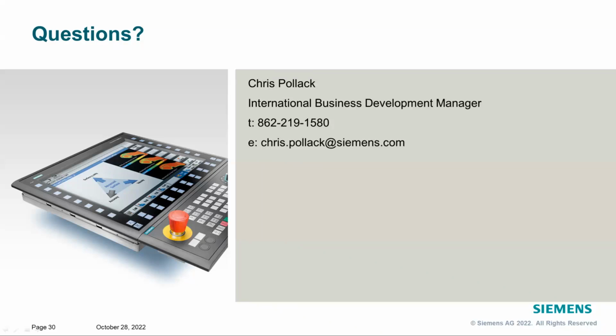Can you hide the machine outer framing? Probably asked that question before I showed it. Yes, with the toggles. Is there a way to clear out collisions after the VCP file grows into a monster? Yes, this is true. The collisions will stay. If you want to keep saving your collisions, it'll keep building, but it will make the file pretty large. So I would say get in the habit of clearing out your collisions from time to time.